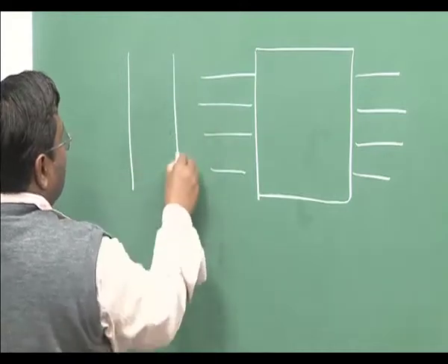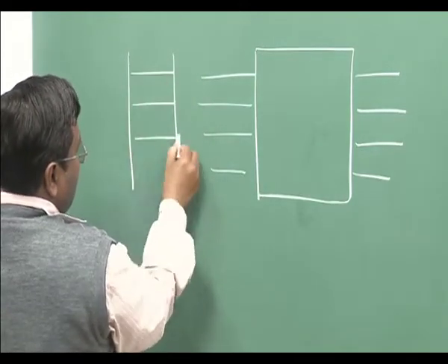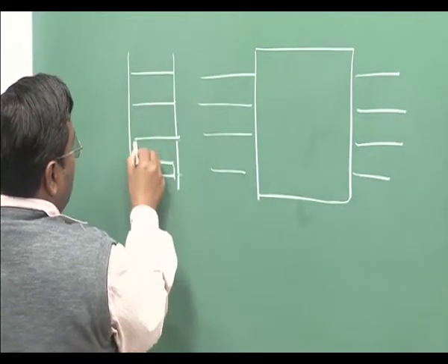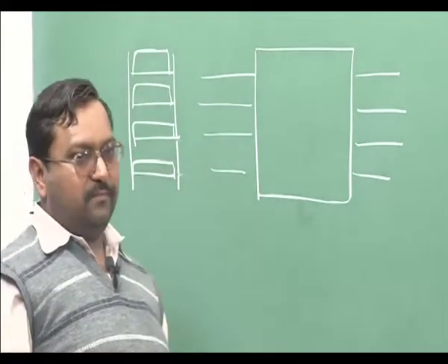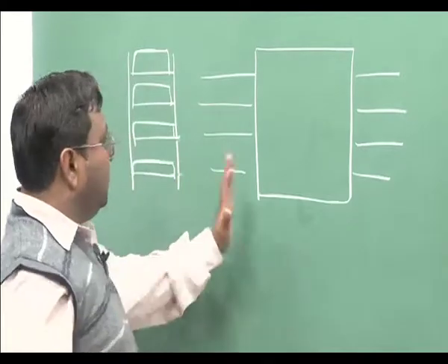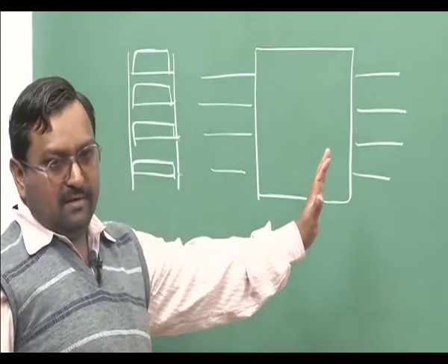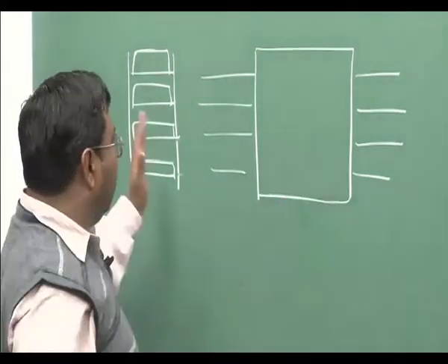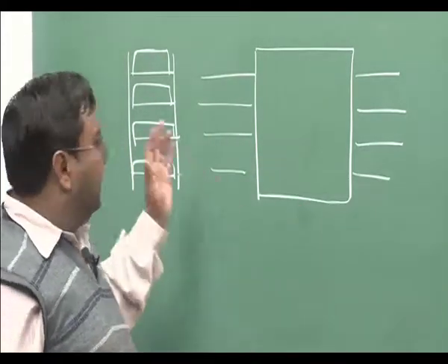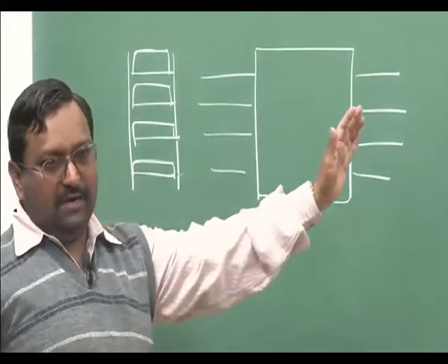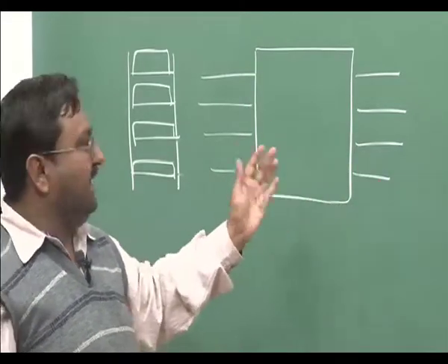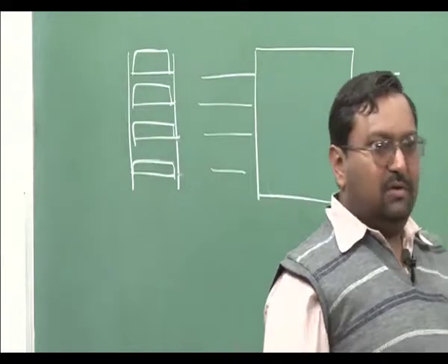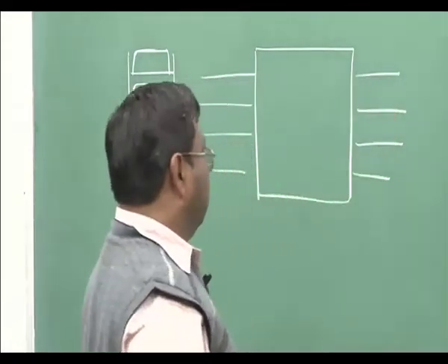And what we had was that all the packets will be coming in synchronized slots. So at the beginning of the slot you will set the crossbar, depending on whatever cross connection you require, and the packet will move through. Then the next slot will come, again you will do the same thing, and so on. You will keep on doing it, and every time the packets will be switched out to the appropriate outgoing ports.